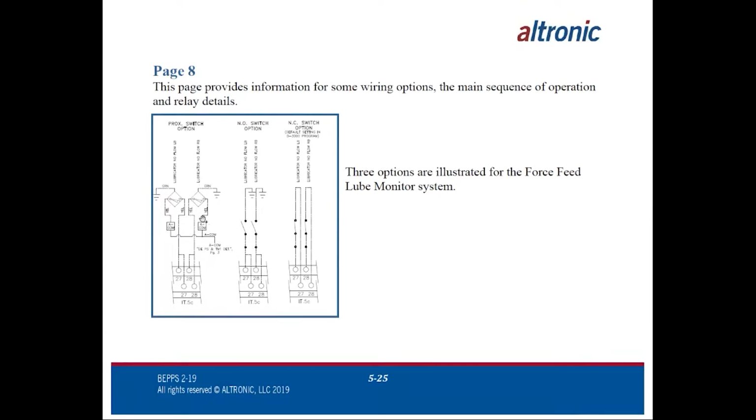Now, this drawing stemmed from a very early drawing with a proximity switch, and it doesn't necessarily have to be done this way. What they're doing in this one is jumping the two 27s together, going one wire out through the proximity switch, returning, and going into ACOM, or battery ground. Most of my guys that I deal with on a regular basis don't even look at this. Most proximity switches have a pair of yellow wires. They wire the two yellow wires straight to channel 27 with no jumper. Works just fine and dandy. In fact, it's an easier way.